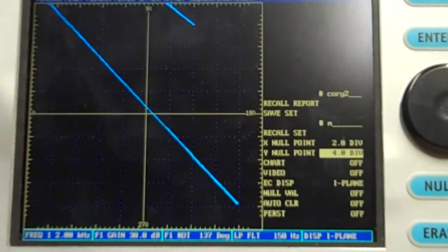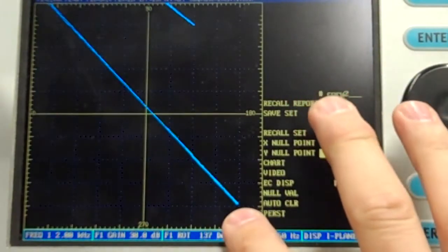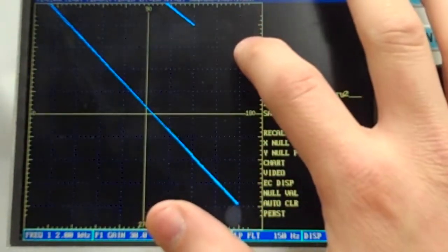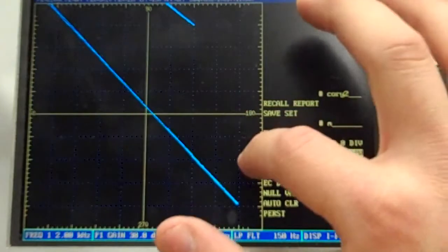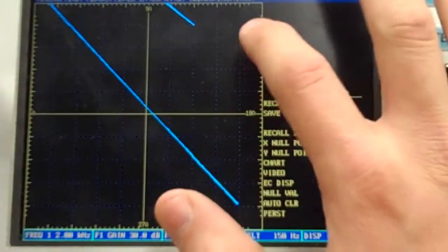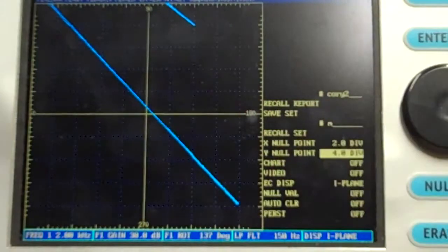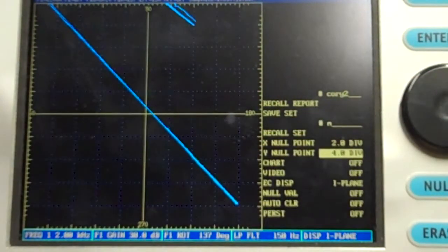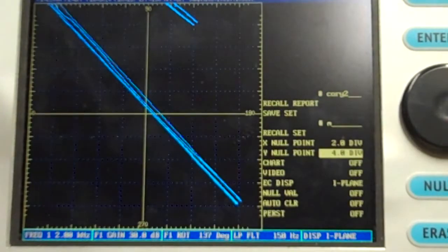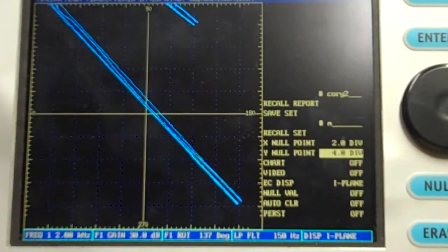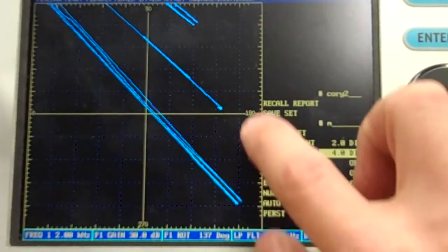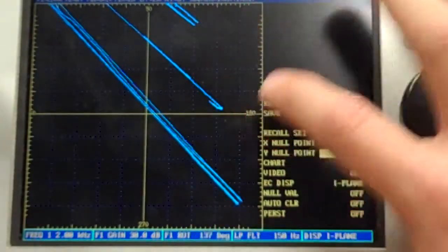Alright, so now since we've blown that up, we know that that conductivity down here has got to be something like, let's put a number to it, 45. So 35, 45. So we've got 1, 2, 3, 4, 5, 6, 7, 8 screen divisions. So let's go 1, 2, 3, 4 right in the center. Let's say 4 screen divisions in this case is 5% conductivity. So 35, 40, 45. So if we could find something here that was right on that 40% conductivity, which we don't have anything right here right next to us. Maybe we do. That's pretty close right there. Coming in right about 40% conductivity, so now we've got 35, 40, 45.